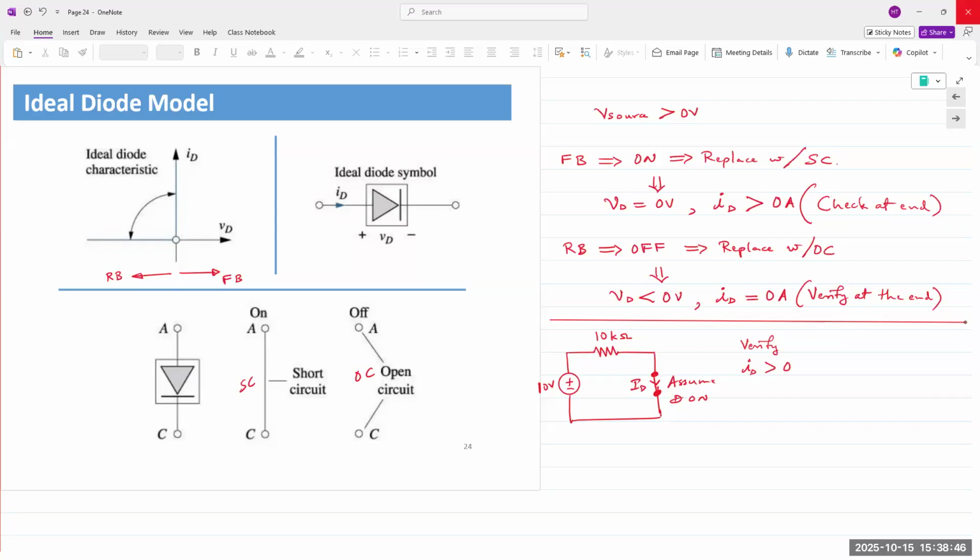It's easy. Current is automatically limited, okay, because the voltage is limited. So if you design a circuit that way, you might be able to get away without using a resistor. In the lab, however, we have these benchtop supplies. It's very easy to oversupply voltage and current to the LED. So the answer is yes, to limit the current.